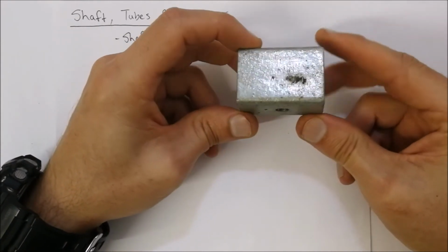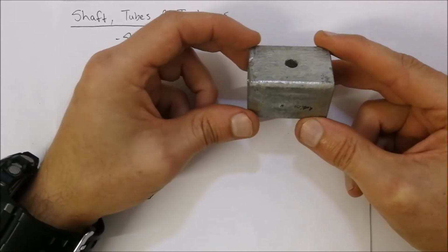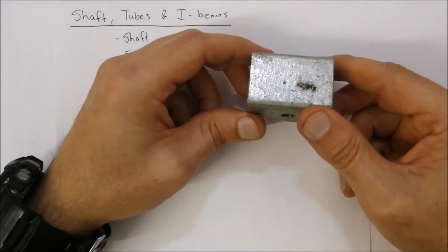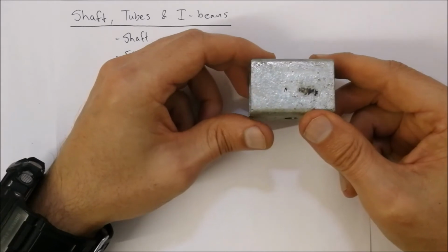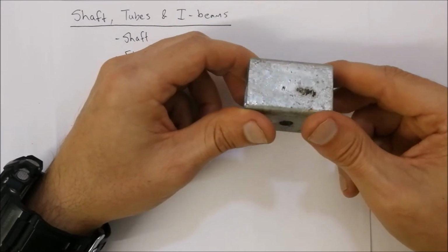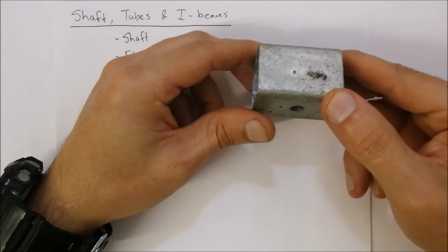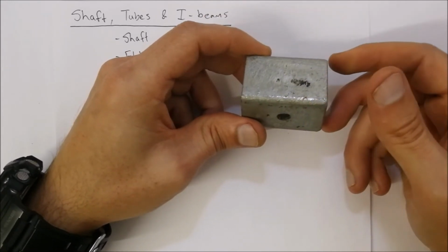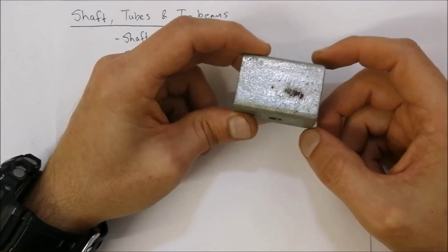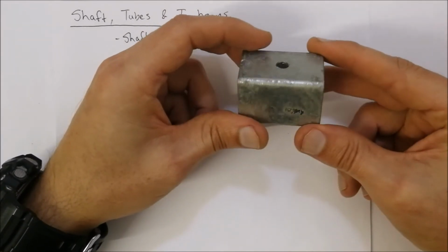and so it protects your mild steel very well. Often you've got some mild steel and you need to have a wire soldered to it, and what's quite useful is you can dip it into copper sulfate, for example, in a solution, and a copper layer will go over it, so that will also protect the mild steel. Or you could even do some electroplating and allow it to solder onto the steel via that little layer of copper that's been electroplated. Okay, so galvanizing is quite useful.